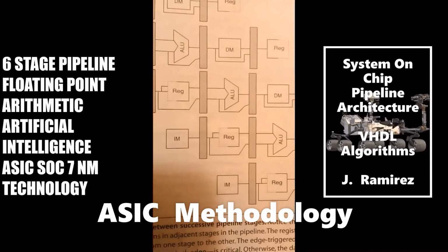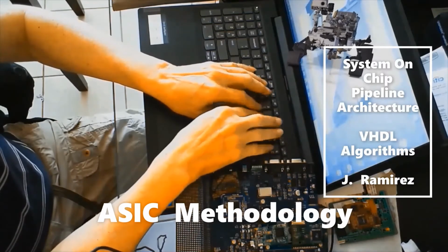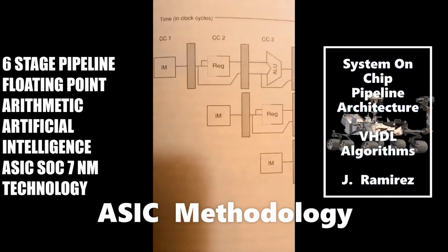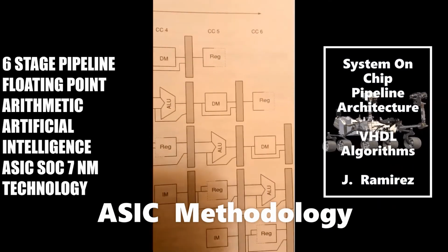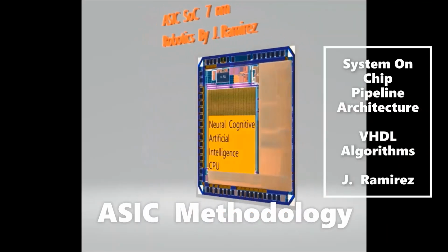The write back stage writes the calculated value back to the proper register. It has input control lines that tell it whether this instruction writes back or not, and whether it writes back the arithmetic logic unit output or the data memory output.